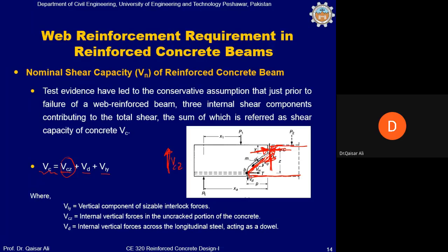In the shear, this will come from friction. When these 2 blocks are compressed against one another, Vcz is the resistance in shear. If these 2 blocks slide against one another, the resistance will be the resistance due to friction, which is produced by these compressive forces, and it will resist this shear force V, and this will be equal to Vcz. Vc, because this is compression, and Z is the vertical direction of this.